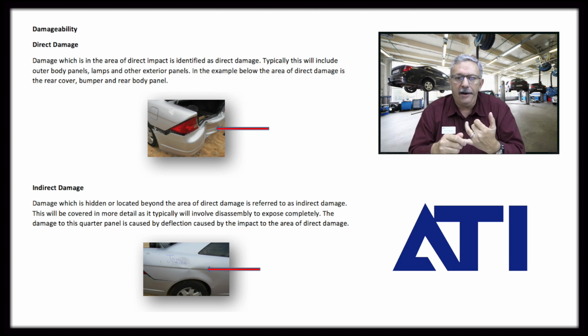That includes things like wire loom fasteners, and in the case of the rear body panel, which we talked about earlier, a lot of those come with a welded on wire loom holder from the factory that does not come on the replacement part that you would order as a crash part. So we need to keep in mind that the removal and reinstallation of that loom, which requires a spot weld, there's 2 of them, and it requires a spot weld on each one of those are not included operations. So the removal part of it and then the reinstallation, we need to add that to the estimate.